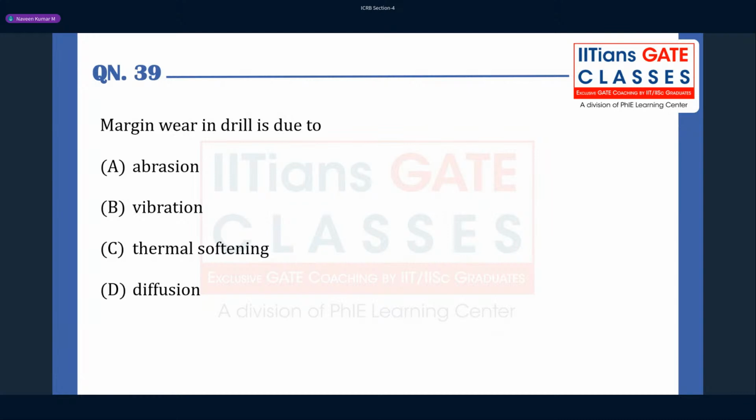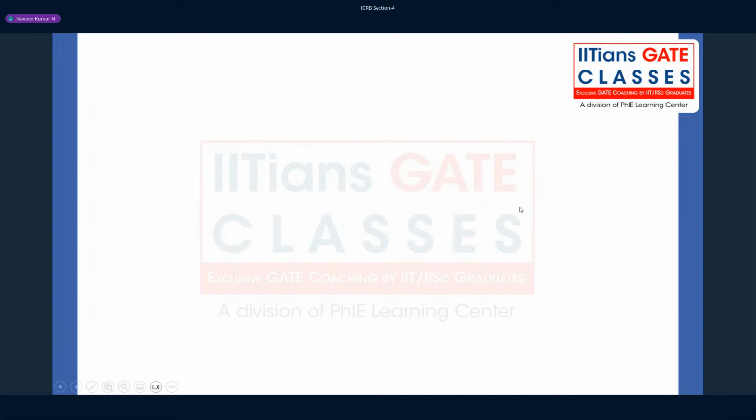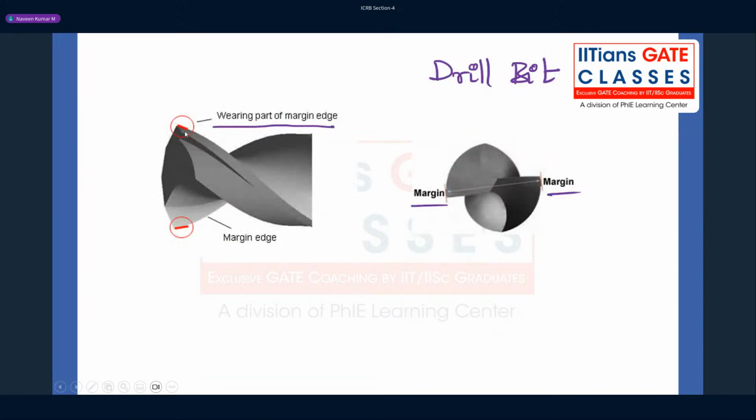So when you're putting the drill bit into your workpiece, we do not know whether the surface is abrasive or it can be softer also. So that will not be the answer for the margin wear. Margin wear is happening here, where the hard hitting is happening, tuck, tuck, tuck. That is where the drill bit comes in contact with the workpiece and where the chips are coming out through these flutes. These are called flutes.